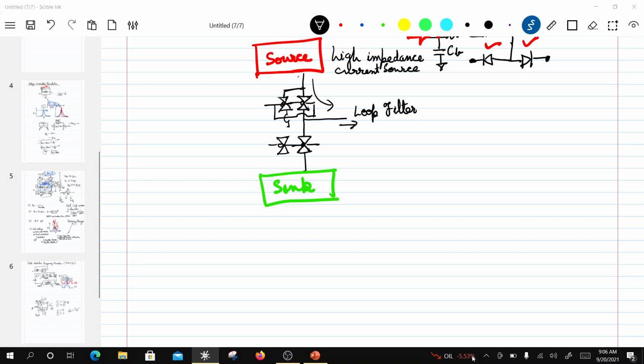you know, sunk somewhere, and this basically is done by a MOSFET here. Okay, so I am going to connect this MOSFET as a diode, right? So this is how the pull up is going to take place. Either the current is going to the load, or the current is steered this way to ground, right?